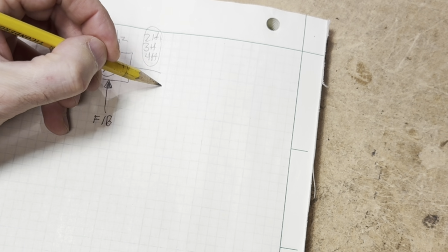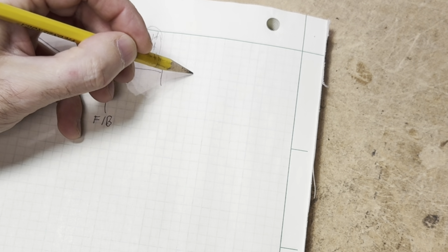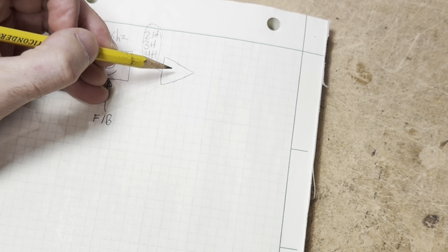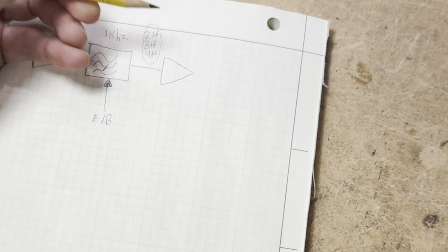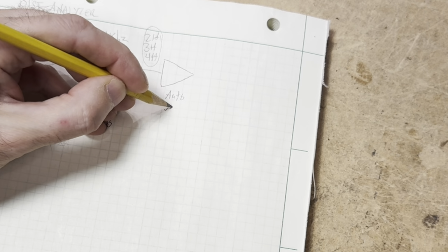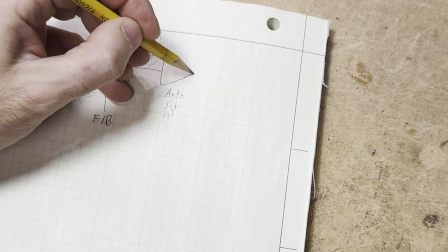So as we shift the level, we need to correct for that level. And the way we do that is we have some sort of level control system at the output of our notch filter. In the more modern instruments like the HP339A, this would be called your auto set level. In the case of the HP334A, this is done manually, but this is going to be a level control system.